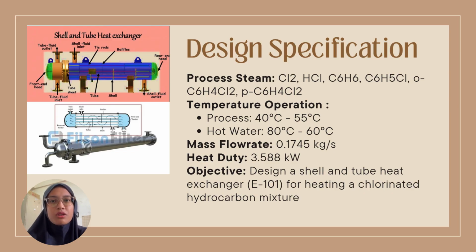The mass flow rate of the process stream is 0.1745 kg per second and the required heat duty is 3.588 kilowatts. The main objective of this design is to develop a shell and tube heat exchanger that can efficiently and safely heat the chlorinated hydrocarbon mixture to the desired temperature.